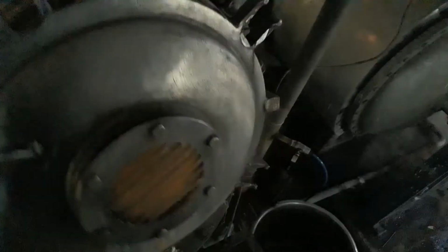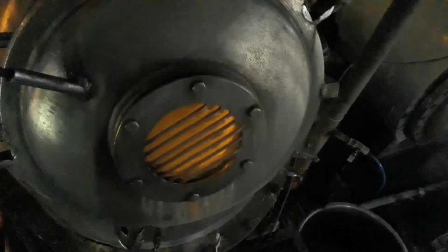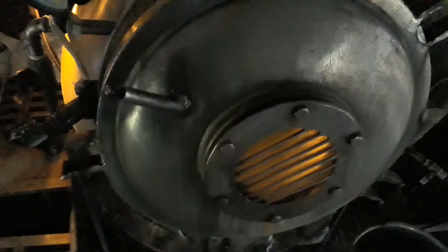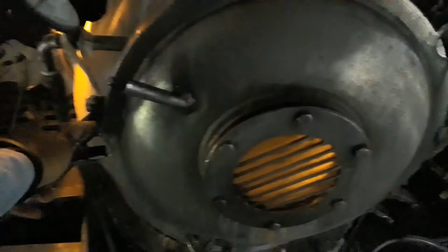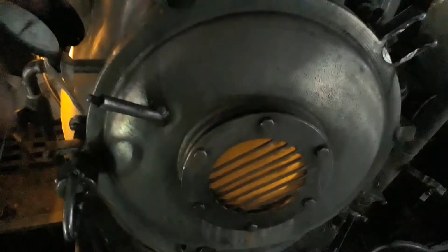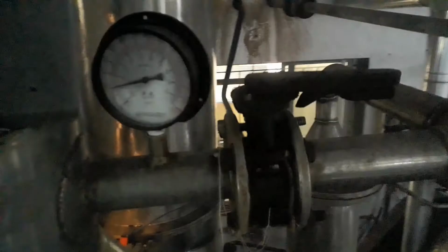The jet is a device where a Venturi effect is applied. When the pump forces the water inside the jet, there is a sudden tapering of the diameter of the pipe, and it creates a Venturi effect. There is a high pressure under which the fabric moves along with the dye solution. So that is the jet dyeing principle.